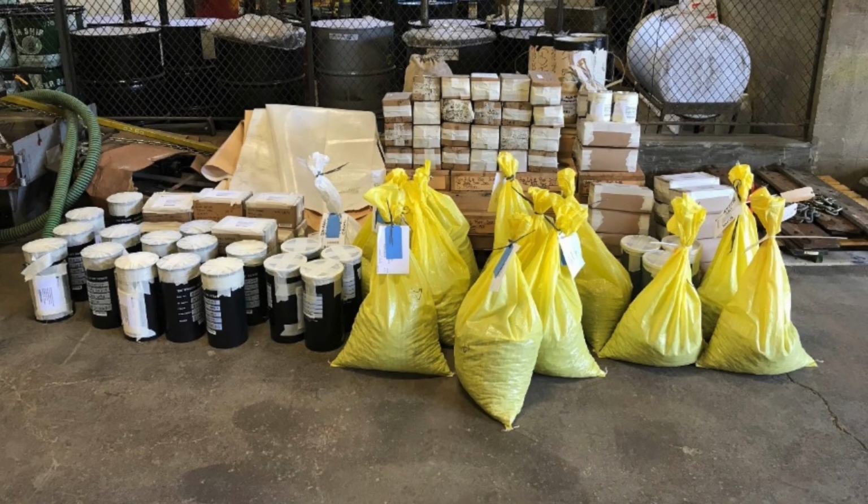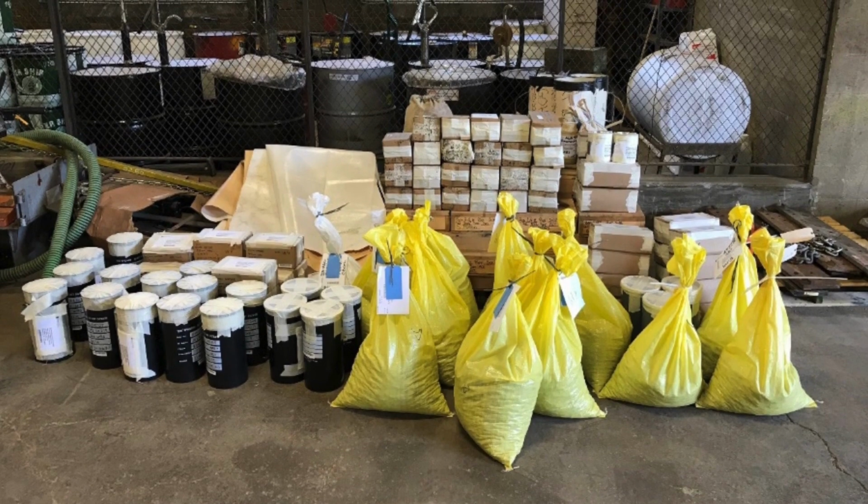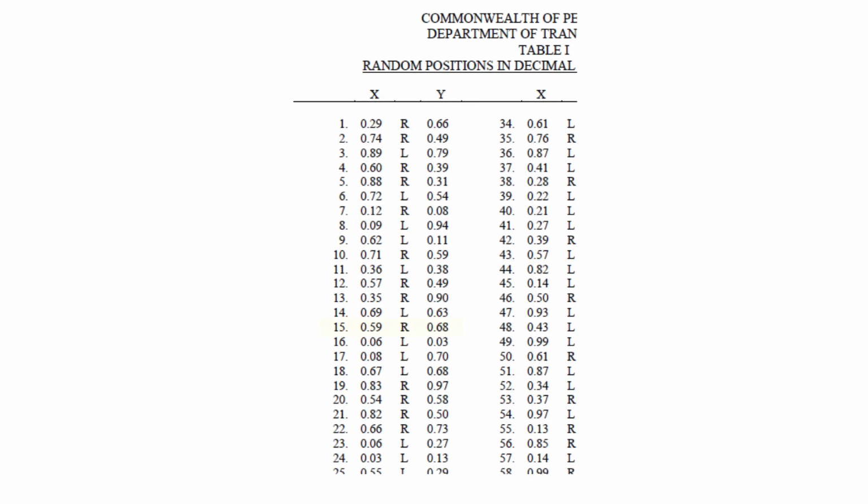After the sublot size is determined, the sampling location for the loose box and core within each sublot must be calculated. To calculate this, PTM number 1 is used to ensure sampling locations are selected in an unbiased manner. To begin, select a random number between 1 and 100. Use that number as the starting point for the lot and use consecutive numbers after for each sublot. In this example, the number 15 is used, and we will assume that there are 5 sublots. Therefore, numbers 15 to 19 are the random numbers for the lot.